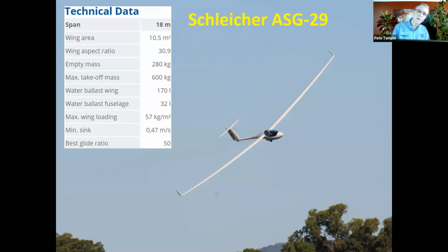So even in this glider, designed something like 15 years ago, the wind is laminar over almost the entire bottom surface of the wing up to a few centimetres from the trailing edge of the wing. Anywhere where the airflow over the wing is turbulent generates drag, so that's a bad thing. So if they can get that as far back on the wing as possible, then that reduces the drag, increases the glide ratio. On the top of the wing, it breaks away and goes turbulent somewhat forward of that point, but there's been big improvements in recent years in terms of the CFD and the performance of the glider wings in particular.